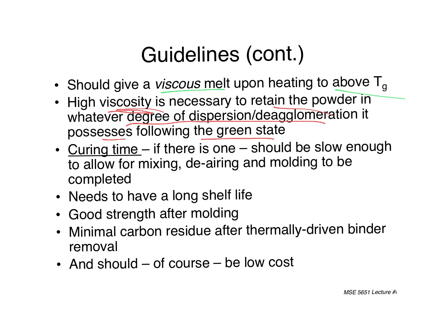And so last time we talked about various things. Brownian motion, slamming particles together, causing them to fall into the energy well and get stuck. But now, what this refers to is the fact that if we have polymers in that system, the polymers get in the way, and they keep particles from getting close enough together to be stuck in that hard energy well. Because these are high molecular weight materials, if Brownian motion drives two particles together, it's not enough to push the polymer out of the way. Water maybe, or hexane sure, but not a high molecular weight polymer compound. So they're really important in this context.